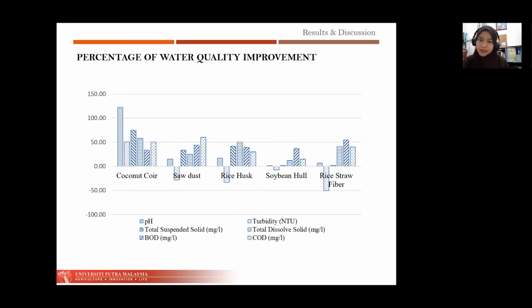For the turbidity, the benchmark was 1.96 NTU, while the rainwater filtered by the rice husk and coconut fiber recorded about 2.11 and 2.95 respectively. This may be due to the dusty biocomposite materials contributing to the increase in turbidity reading.